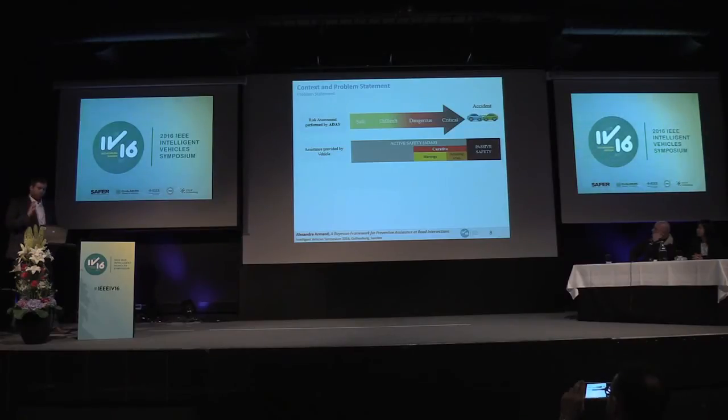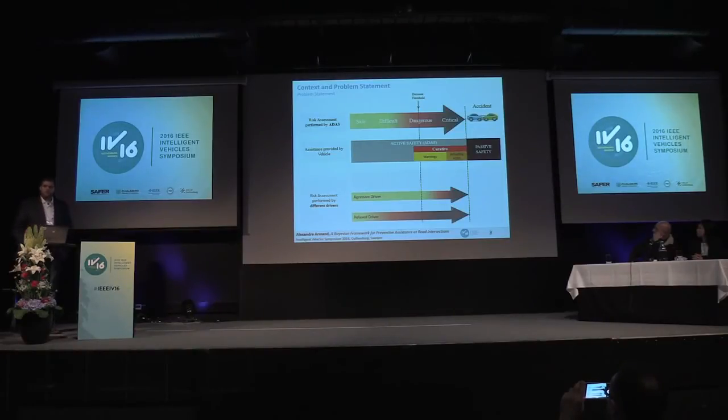Actually, most of the conventional ADAS do not consider the fact that every driver is different. But we know that every driver is different. 2 drivers will not behave in the same manner for the same situation. And the drivers will not understand the situation in the same manner as the safety ADAS. For example, one aggressive driver will consider the situation is safe, while it will be inferred as dangerous by the safety ADAS. And on the contrary, for a relaxed driver, he will maybe consider the situation is already dangerous, while it will be inferred as safe by the safety ADAS.